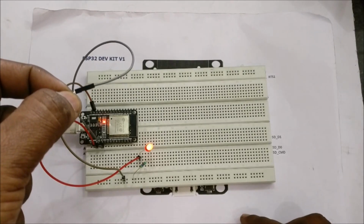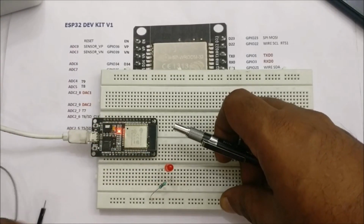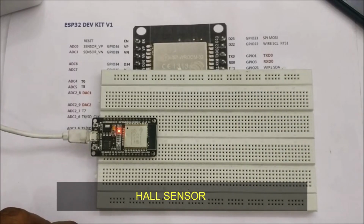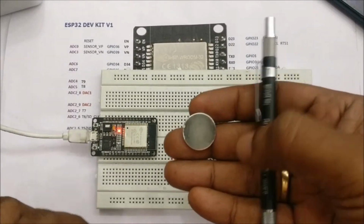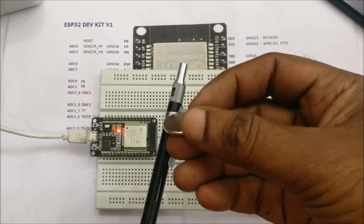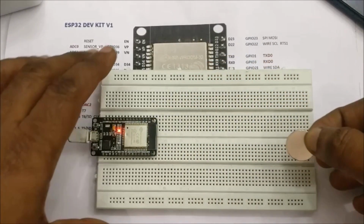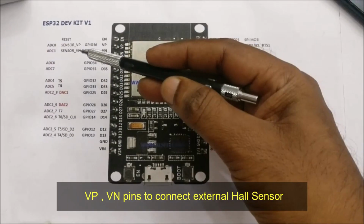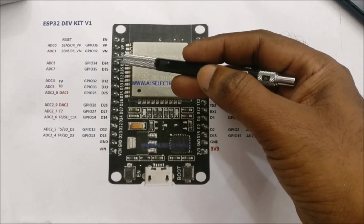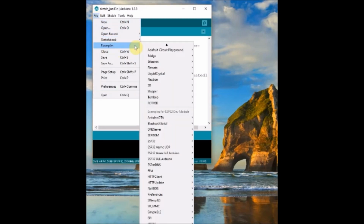The next sensor is the Hall sensor. This is also an inbuilt sensor of ESP32 which detects the magnetic field. When a magnet is brought near the ESP32, it produces a value. We'll be using a neodymium button magnet to test the Hall sensor of ESP32. There are also two separate pins, VP and VN, where you can connect an external Hall sensor and use the ADC of ESP32. In this example, we'll be using the inbuilt sensor.